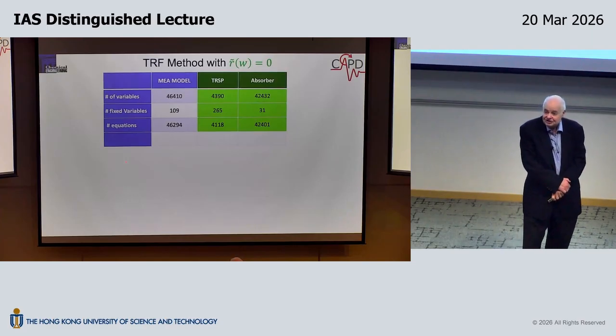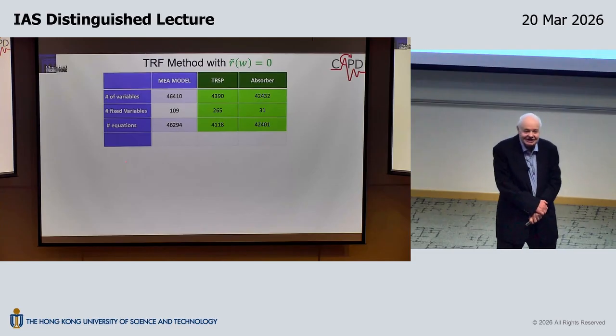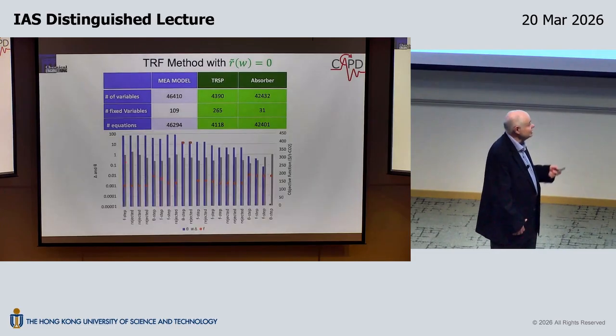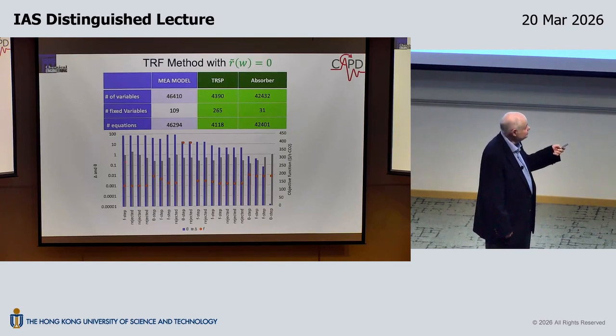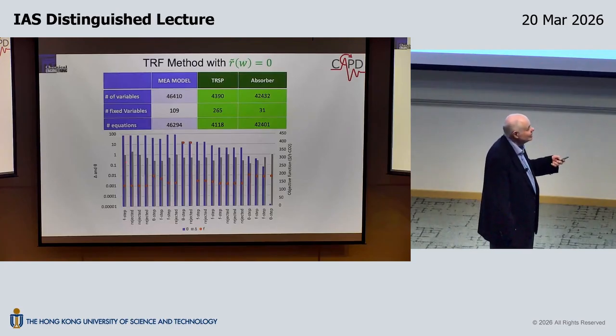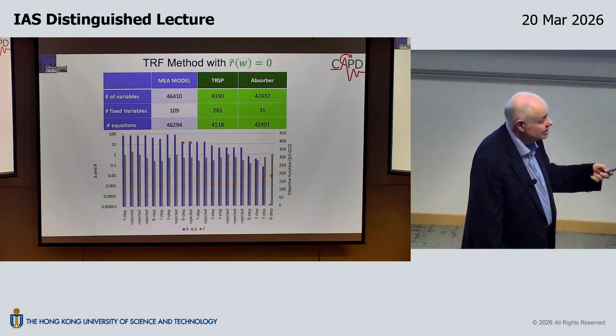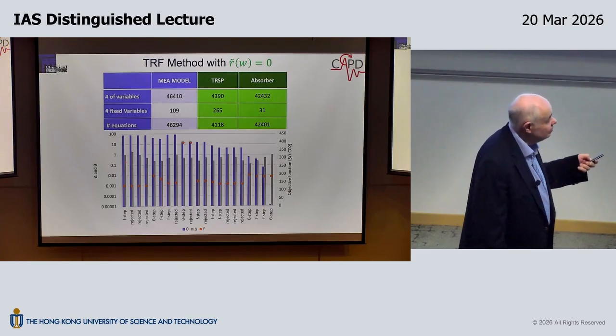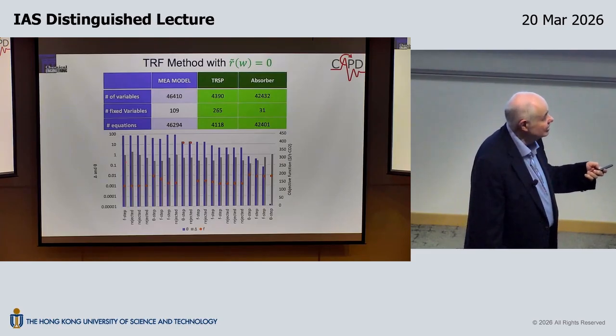If I have a 0 digital twin, okay, nothing except my bias updates, this thing is going to take about 20 iterations, 21 iterations, okay, cycles. The infeasibility here is given by the gray bars, and what I'm seeing over here, actually, no, the trust region is in the gray bars. The blue bars are the infeasibility, and you're going from here down to something that is orders of magnitude less, basically 8 orders of magnitude less in infeasibility, and the objective function basically dithers around and finally ends up at this point.